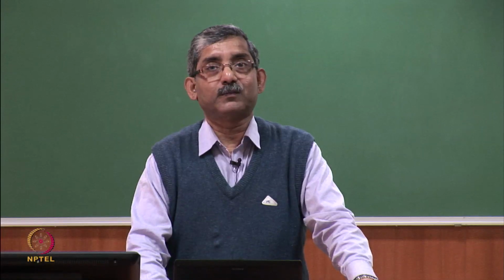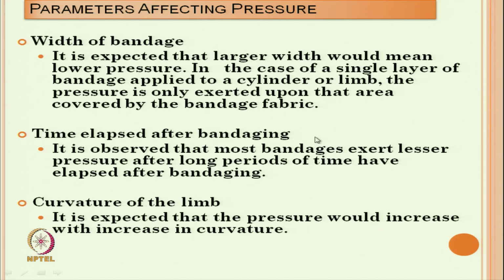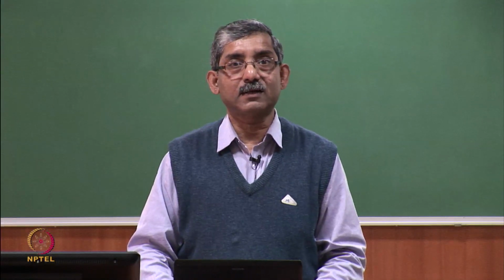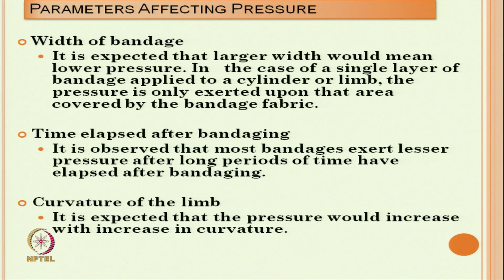Time elapsed after bandaging is very important for retention of compression bandage. As we know, textile materials are viscoelastic in nature, and these bandages will try to relax; there will be stress relaxation in the structure. So, gradually the pressure will reduce with time. It is observed that most bandages exert lesser pressure after a long period of time.